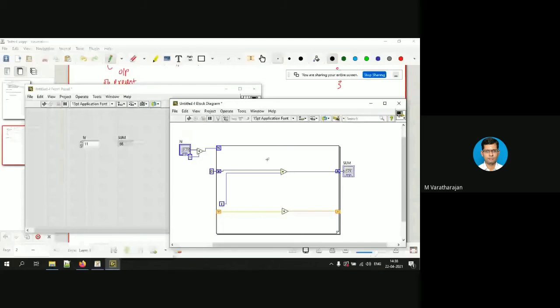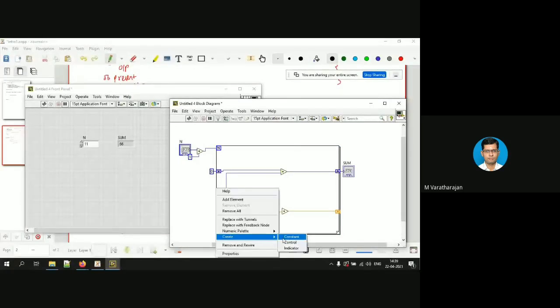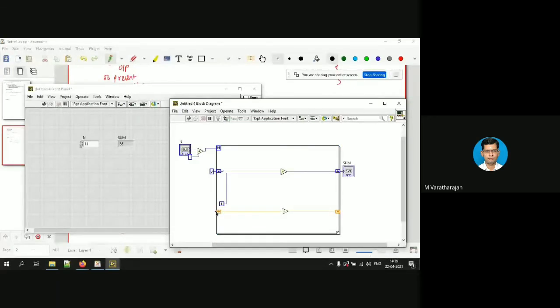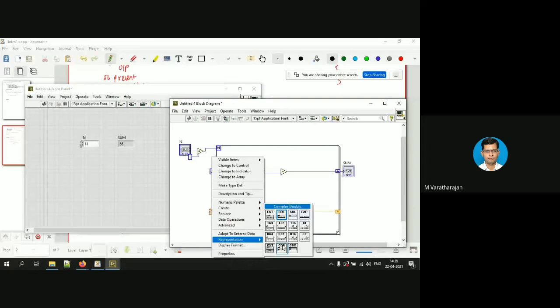Okay. So for this also, the expression evaluation is like the previous case, but the only thing is we have complex numbers, that's all. And LabVIEW supports complex numbers by default. You don't have to do anything special. So for creating the initial value, let me click on the left side of the shift register, create a constant, and this constant is going to be a complex constant. Right click that constant, representation, it is complex double. Once you have chosen it, this particular data will be complex.